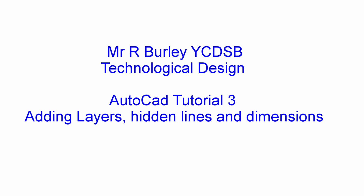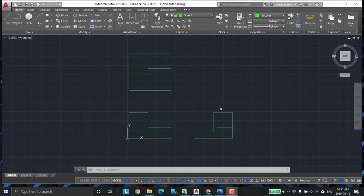What I'm going to do, this is the third video in this series. The first one we drew this, and then the second one we did the orthographic projection with the 45-degree angle and set these drawings, these sections of the drawing. What we're going to do now is we're going to add dimensions and we're going to add hidden lines.